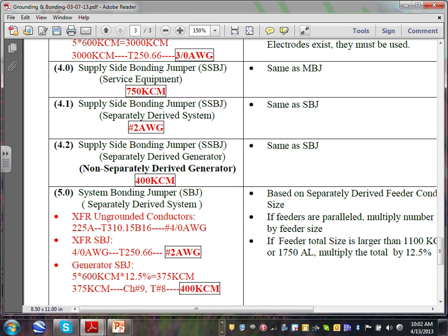You tie your conduit on this side, and you continue. Another fitting right here, you tie your conduit on this side, and you continue. So it's one wire. You pick the conduit from both sides and tie it to the other. So you bonded the conduits, and at the same time bonded the two enclosures.